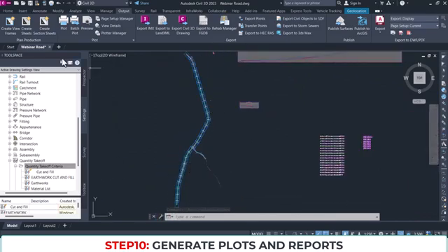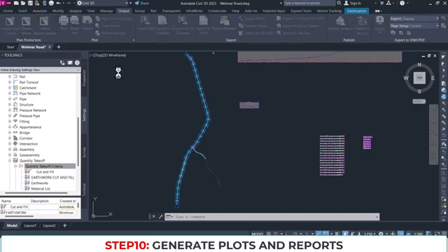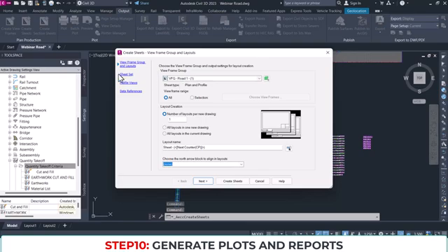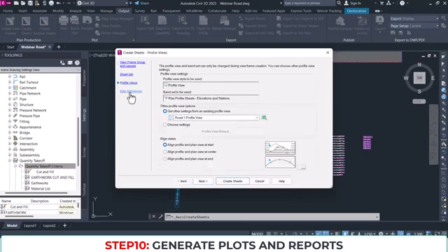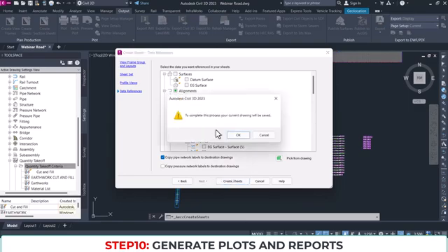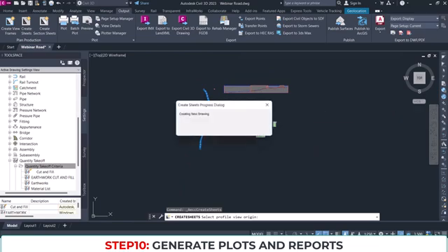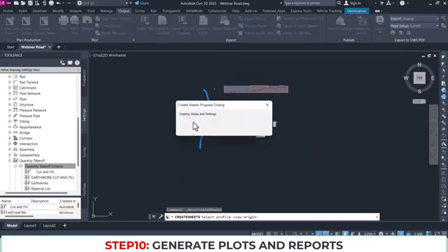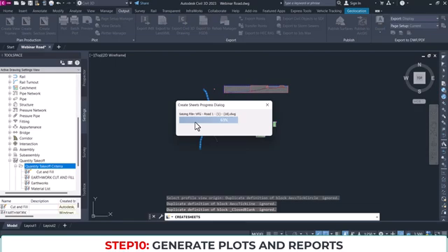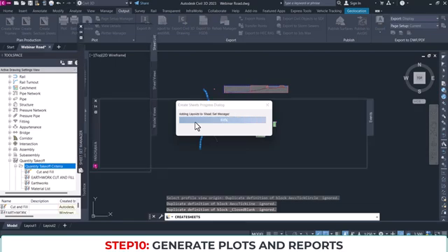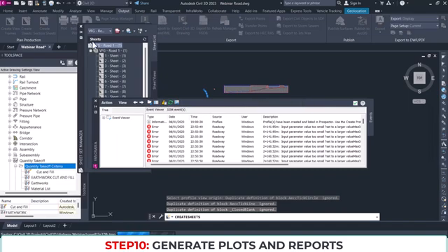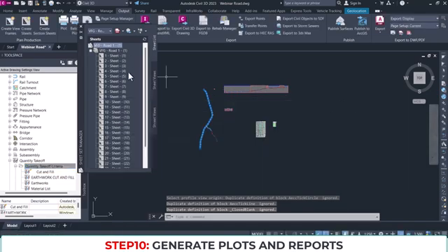So what will this thing do? You have to create view sheets. Create sheets. So you are going to use the view frame that you just created and then create sheets out of that. Let me create the sheets so that you can see. The drawing has to be saved. So I should look for somewhere and click on the screen, and then it will create the sheets for me automatically. Alright, so let's wait for that. Great, it has created the sheets as a separate drawing. So it's saved somewhere in your file.